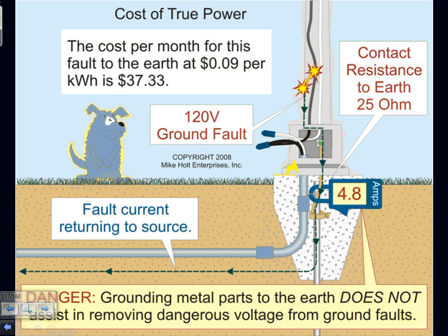I want to remind you guys, you only pay for the true power. You don't pay for the apparent power. So for example, if I ask you, 100 volt amp, how much do you pay for 100 volt amp? You say, Chad, give me the power factor. That's just the potential use. I need the power factor. If I told you the power factor is 70%, great, now 70 watts.